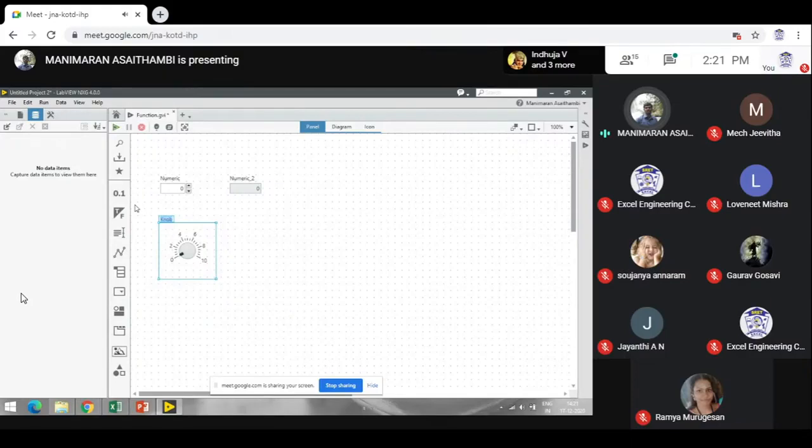Now if you see, for number 2 here, I connected to numeric, and the knob I connected to the pressure gauge. I'll take this boolean button and connect it to the round LED there. So boolean to boolean, it connects. Do you see the different colors represent different data types? For number it is orange color. For pink it is, for green it is boolean. So there will be a pink color.